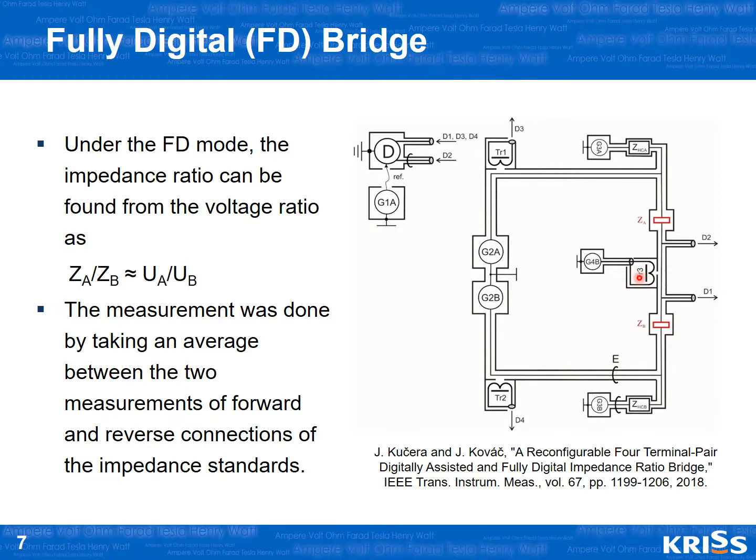In order to switch the measure point during the balancing procedure, a coaxial multiplexer is embedded. The bridge can be controlled remotely via the LabVIEW software. The automated process enables the impedance ratio measurement by one click within a few minutes.